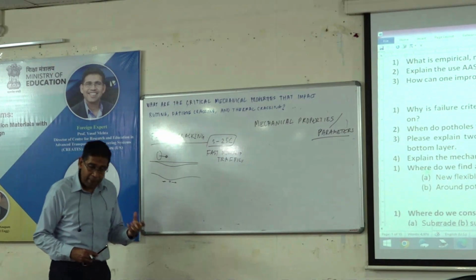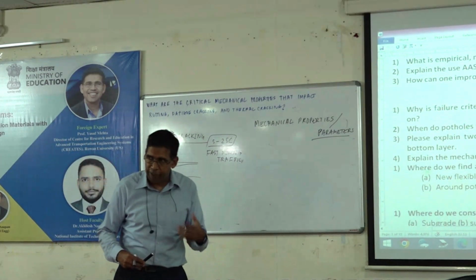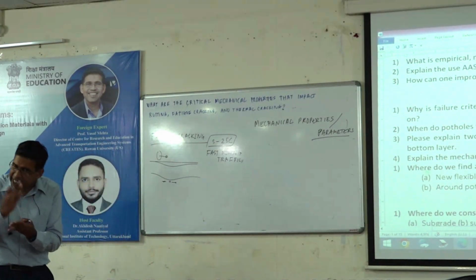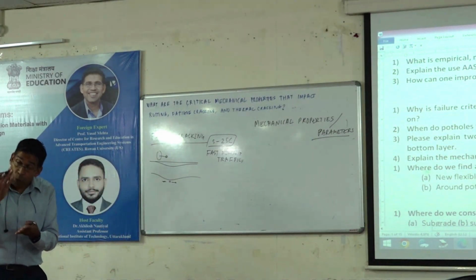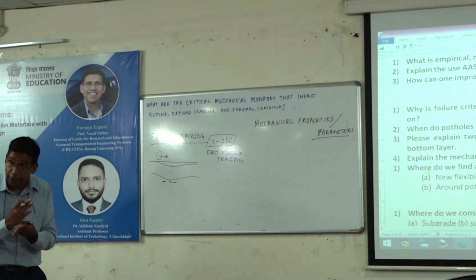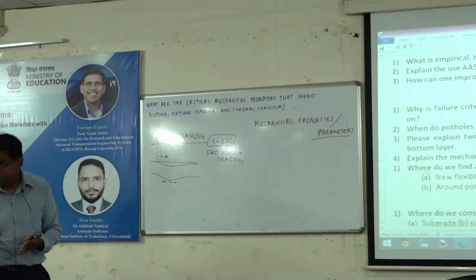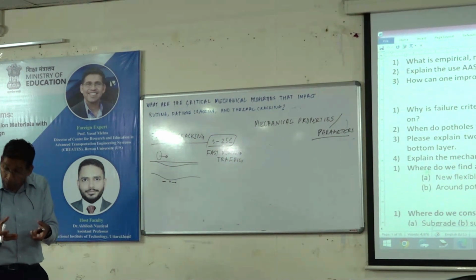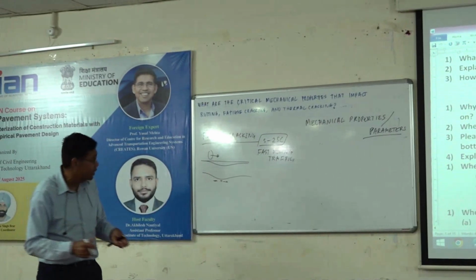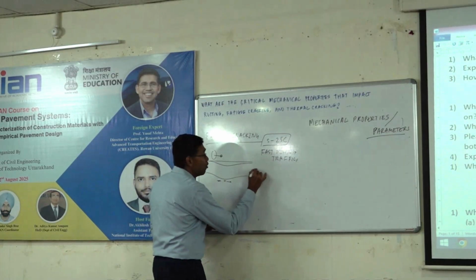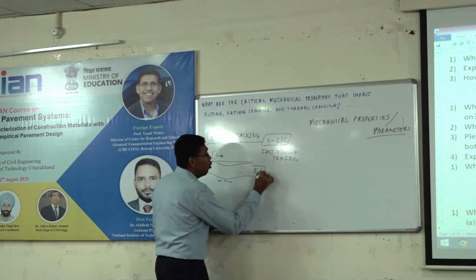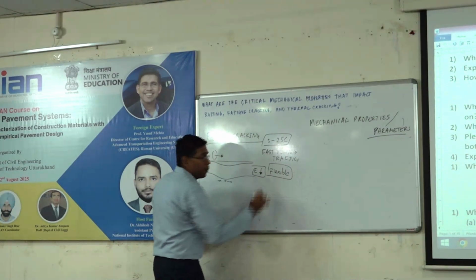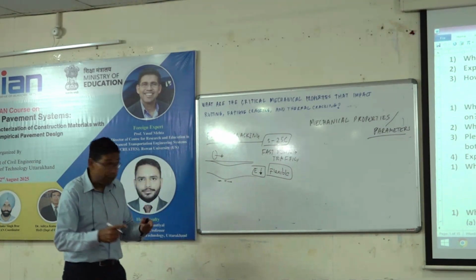So the example I give is that you want the material to be flexible, right? It's going through repeated loading, so you are hammering this again and again, right? And you want that material to handle that deformation without cracking. A flexible material like a rubber band can go back and forth and handle this. So you want the E value, the flexibility, you want the E to be low, you want it to be flexible. Does that make sense? It's exactly the reverse of rutting.